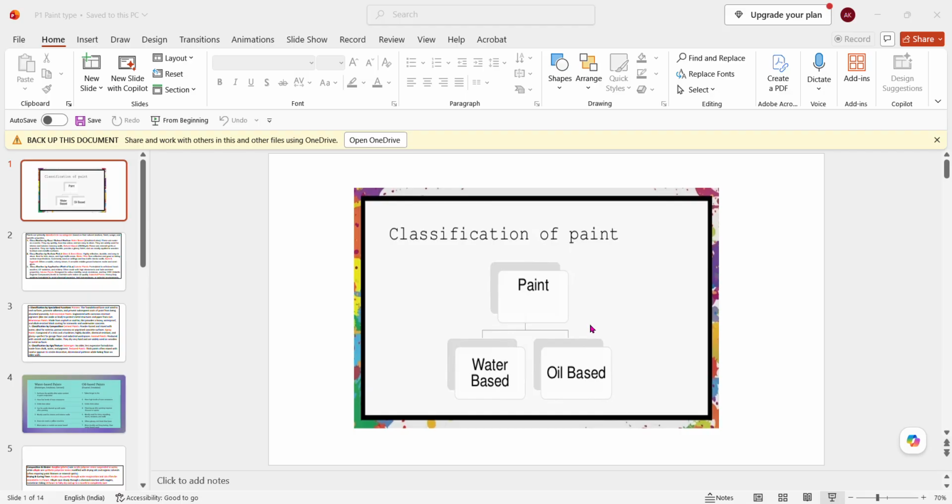This is anti-corrosive paint. And synthetic rubber paint also can be used, with different colors of pigment. Rubber paint is formulated with dissolved synthetic resin and suitable pigment, so the color can be attained. You will find this paint on concrete surfaces, such as walls or floors.